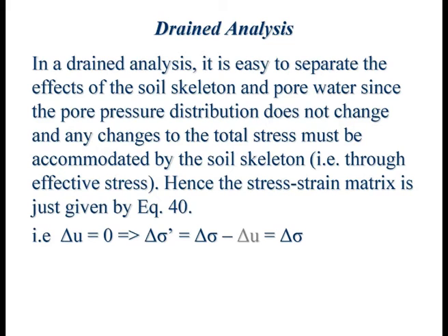In most cases, the boundary condition can be quite straightforward. You start with the hydrostatic, you end with the hydrostatic. But in some cases, it's not so straightforward, because when you dig a hole, inside the excavation, 30 meters deep, the water table is drawn down 30 meters. Outside the excavation, it's still somewhere high up. So what happens between this side and that side? The water will start to seep.